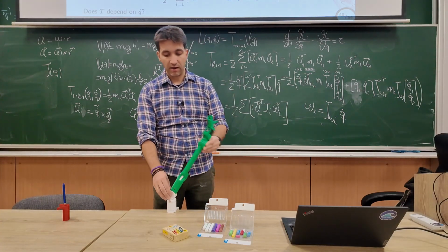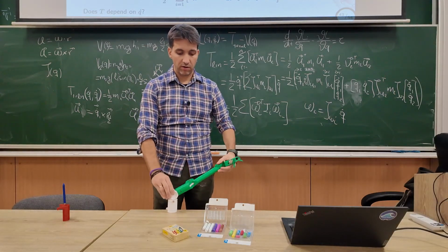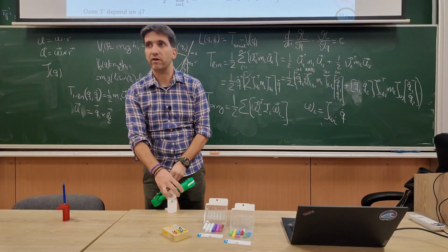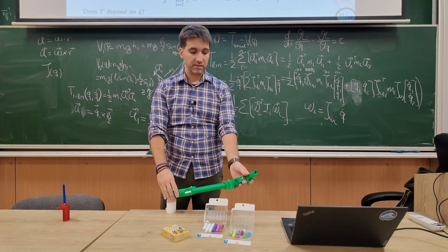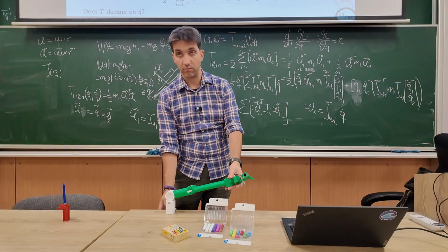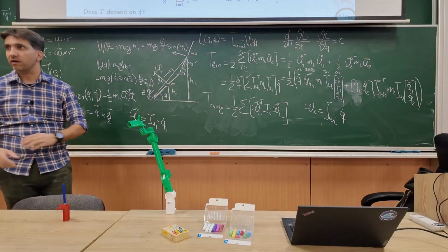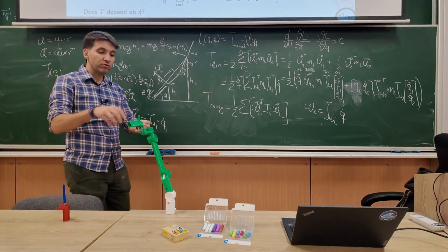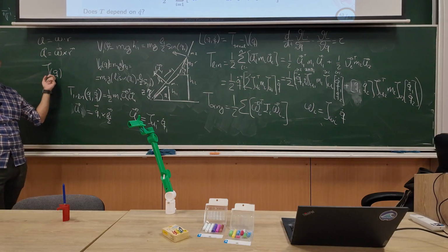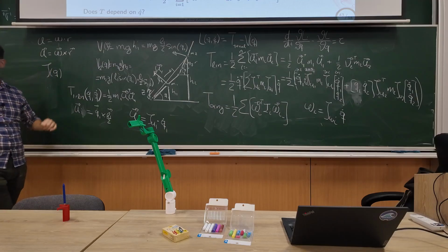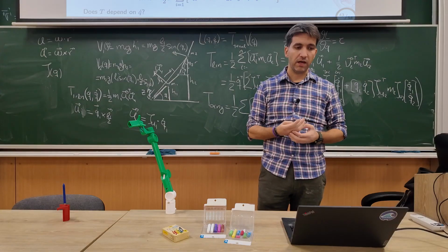So then, for the same angular velocity, I will have more or less kinetic energy based on the joint configuration. Here I present an extreme case, but you get the picture. How come the joint position affects kinetic energy? Because we said kinetic energy is a function of mass and velocities. But basically joint position affects joint velocities and effector velocities, due to the Jacobian being a function of Q. Any questions?